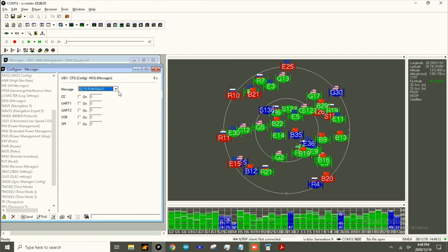Moving on, we'll go to what we call the RTCM correction messages. These are provided by the receiver, the corrections themselves. So once we know the position, we can accommodate the errors induced by atmospheric conditions, gravimetric differences, Doppler, and inaccuracies in the timekeeping of the satellites themselves.